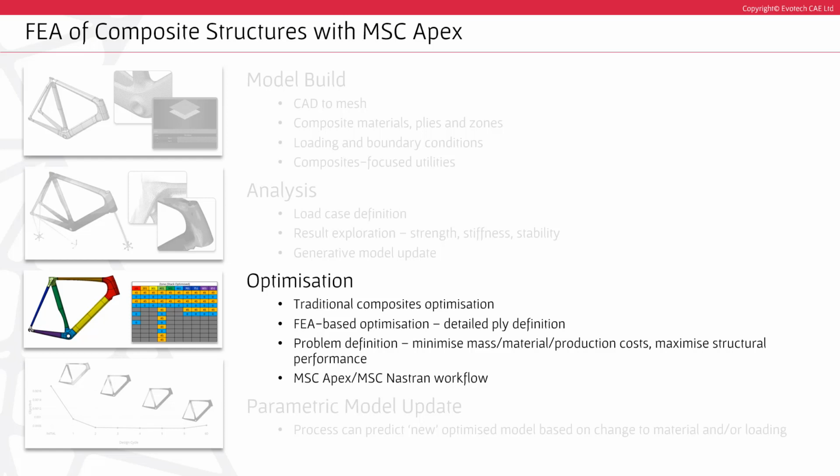In this particular example, we're going to look at how Apex will interact with MSC Nastran from an optimization perspective. So we've got the ability to export a Nastran deck from the Apex environment. We're going to be looking at a SOL200, which is the sizing-based algorithm within MSC Nastran, and we're just going to take a quick look at a web tool developed by a third-party distributor, Engineering Lab.